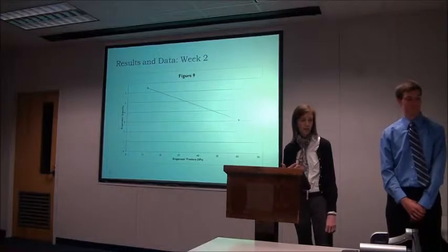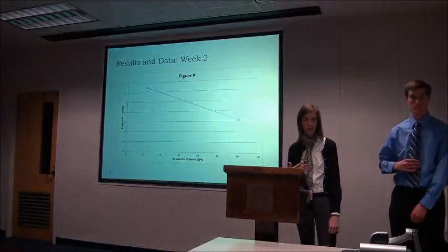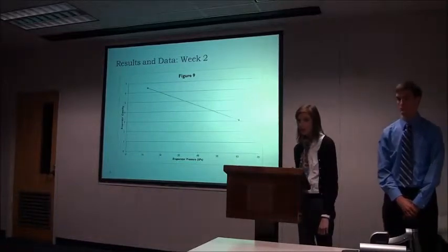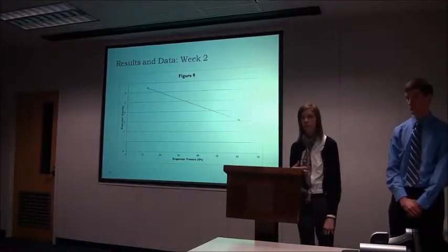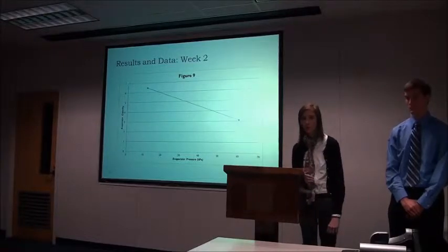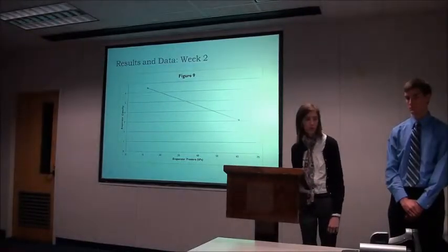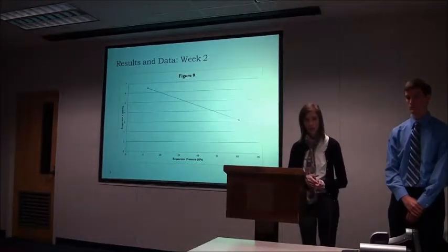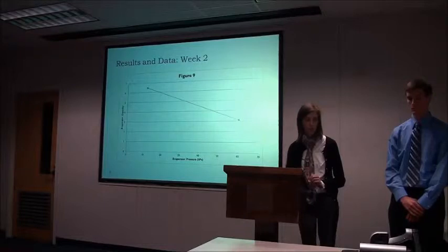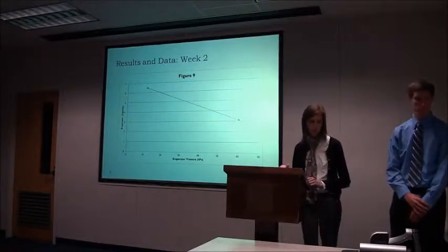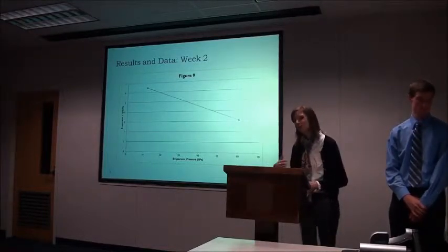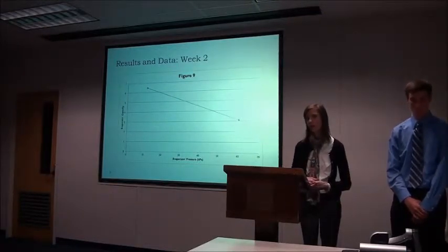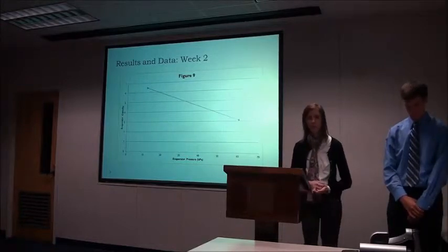And the same trend can be seen with the evaporator capacity. Again, because the economy is V over S_A, or as Scott mentioned, the kilograms of water vaporized per kilogram of steam fed, the capacity is just V, or the kilograms of water evaporated per hour. It also decreases with increasing pressure or less vacuum. So in order to have a better single effect evaporator, we found that running under more vacuum is more beneficial.